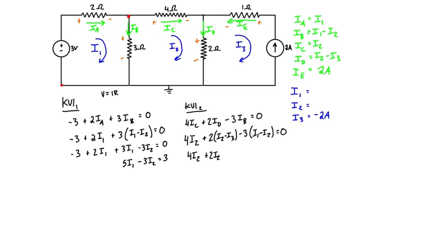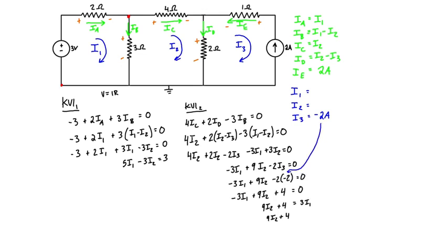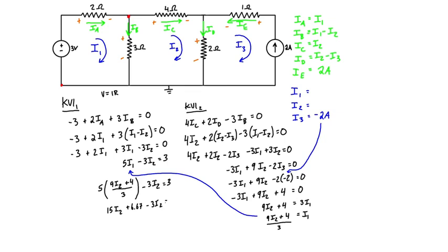And basically, I'll just fast forward, but we can simplify this all down into an expression for I1. And we're just going to take that whole expression and plug it back in right here to I1. And then we can also simplify this down to get I2 is equal to negative 0.305 amps. And then we're going to take that and plug it back into this expression where the I2 is, and we'll find that I1 is equal to 0.418 amps.